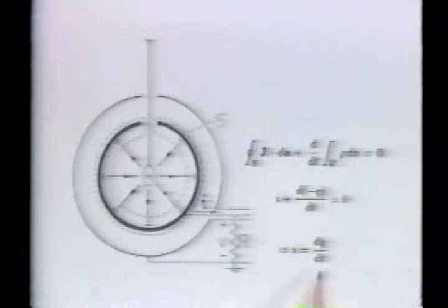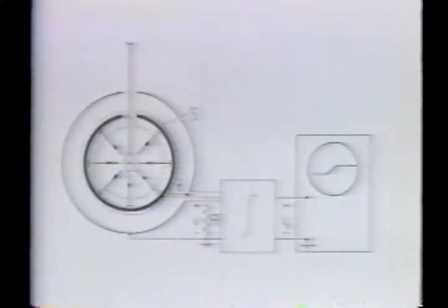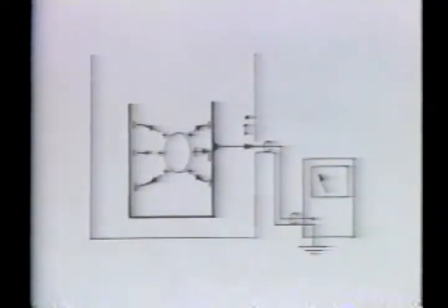The integrator is made from an operational amplifier, and the integrated signal could be displayed on an oscilloscope. Instead, we'll use an integrating electrometer in Coulomb measurement mode. It's designed to display the charge that would account for the integral of the current into its input. The shapes of the Faraday cage and grounded shield do not matter. In our experiment, the Faraday cage is a waste paper basket-sized rectangular aluminum box, and the surrounding shield is a metal screen.